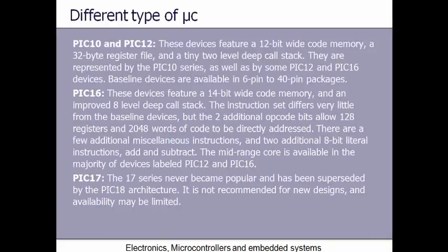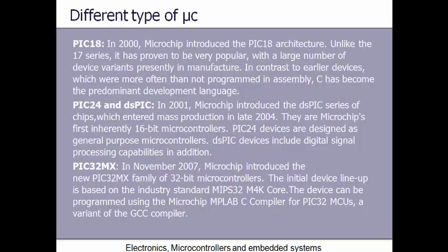So there are many types of microcontrollers or families. There is PIC10, PIC12, PIC16, 17, 18, 24, and recently PIC32. The difference between them is first in the internal memory, meaning the size of the program they can hold, and also the functionality they can offer.